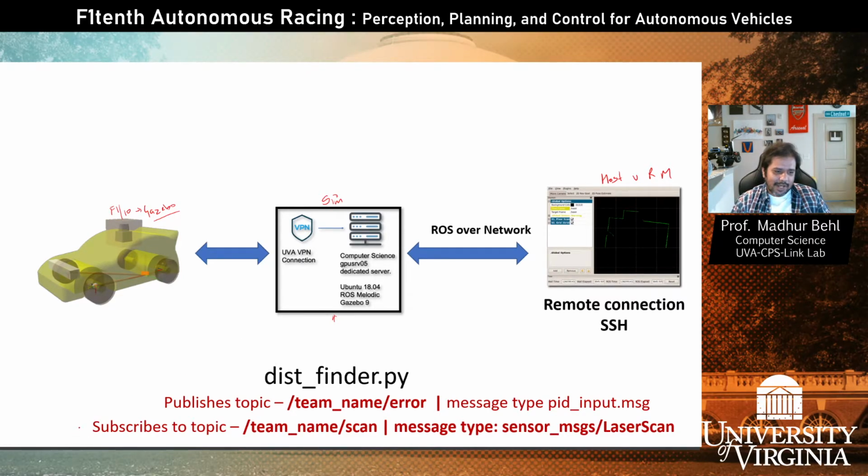It will subscribe to your team name/scan topic, which, as the name implies, is the topic on which the LiDAR messages of your virtual F110 car are getting published. Be sure to subscribe to your team name topic and not some other team's, because these topics are visible, so even by error you could subscribe to someone else.